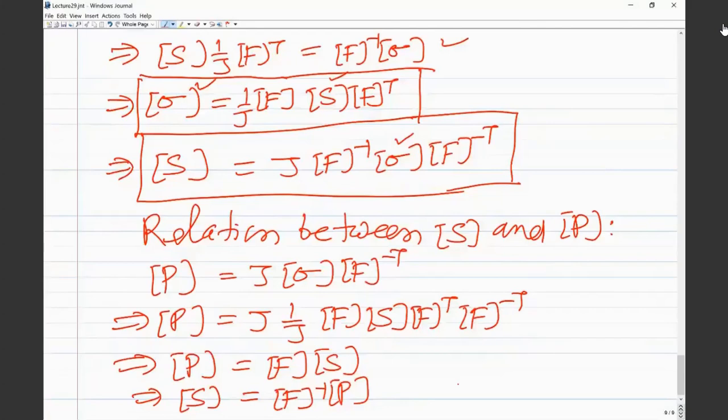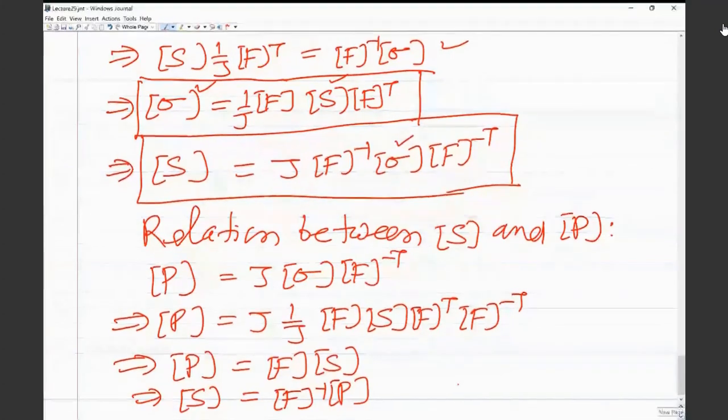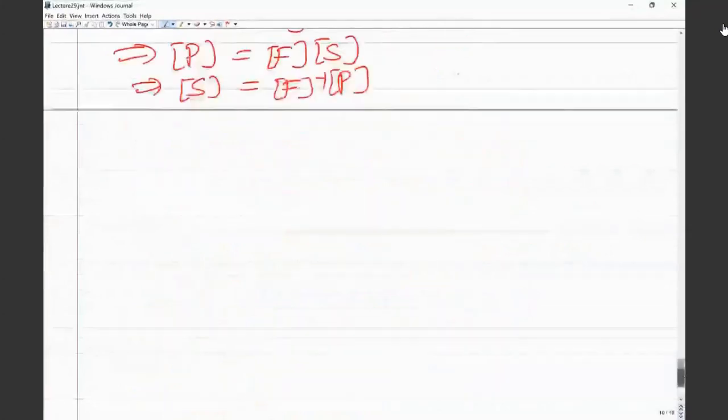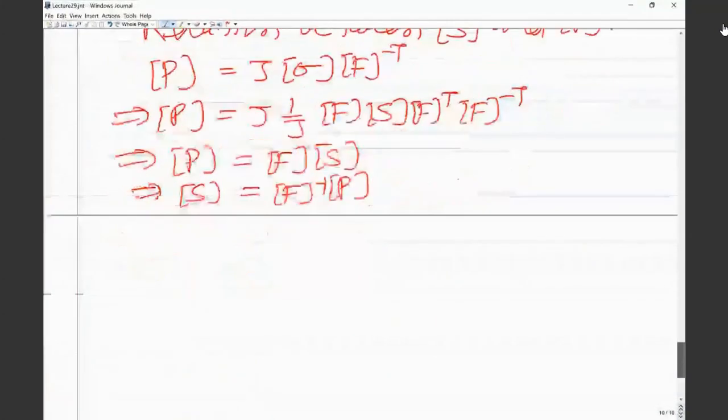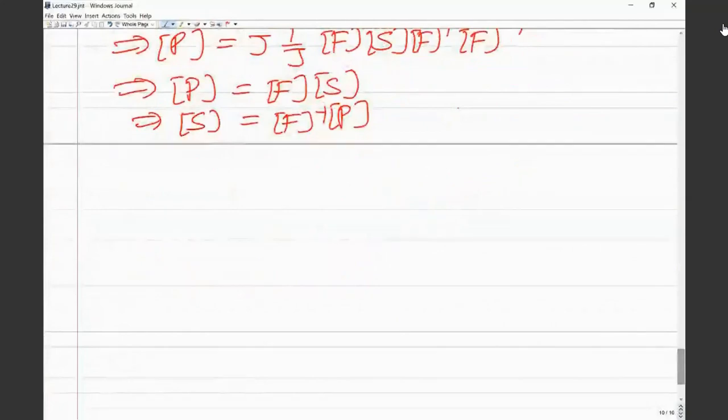So the Cauchy stress, first Piola-Kirchhoff stress tensor and second Piola-Kirchhoff stress tensor will all be the same if the displacement gradients are small.